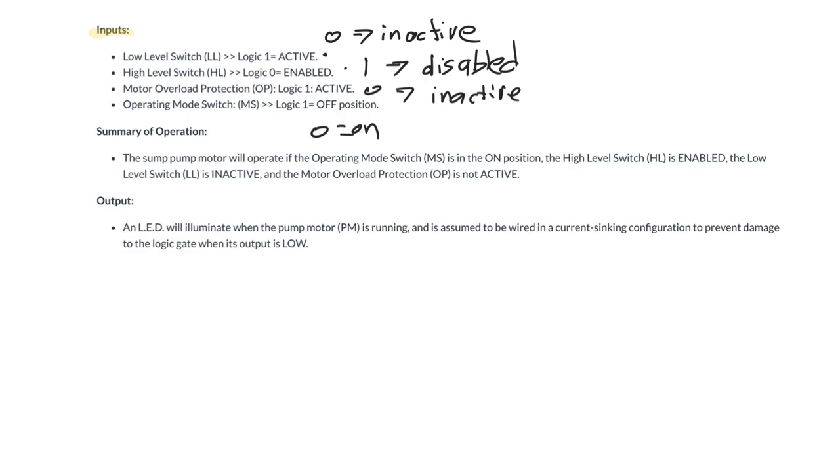If you look at the control statement here, it says the sump pump motor will operate if the operating mode switch is in the on position. The operating mode switch is MS, and if logic 1 is off, that means on must be logic 0. So that would be MS not, like that.